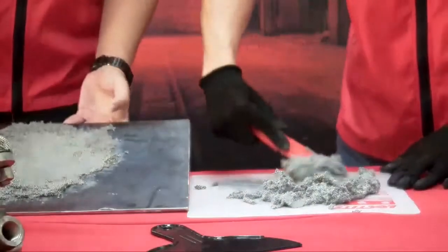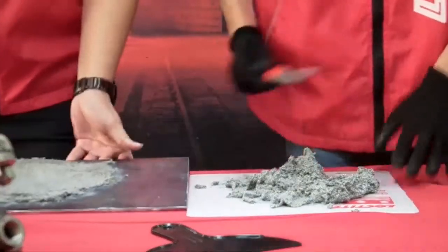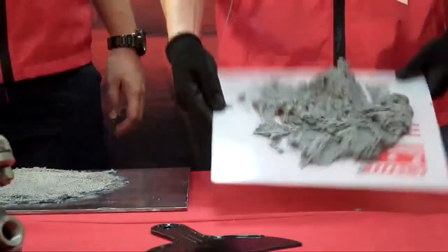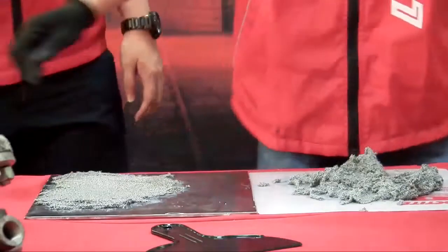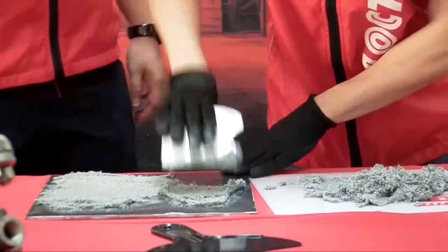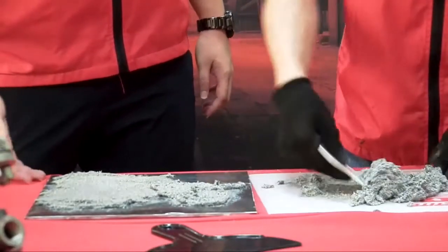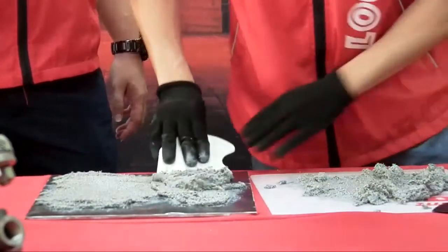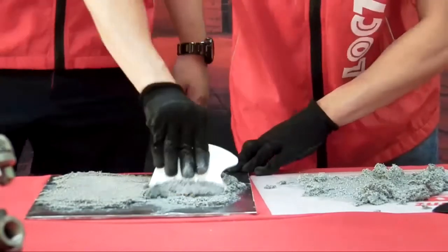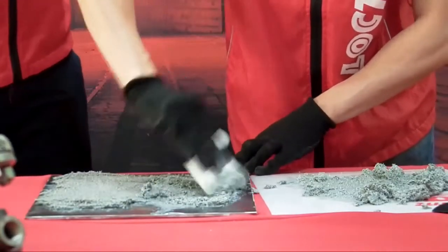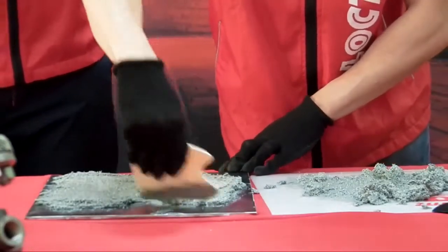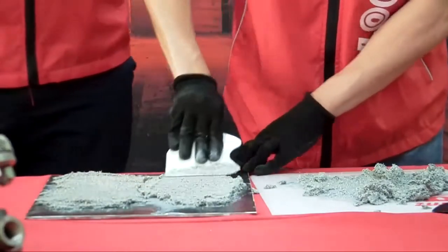Okay, I've already done the mixing. You can see I mixed it quite carefully. Like what Eng said, I'll try to apply to the metal surface first, so that you can see how easily this product can bond to the metal parts. Basically, you can coat this 7226 up to whatever thickness you desire. What we recommend is mostly a minimum of 6 mm. Yes, for these products. Okay, you can see I already applied this product onto the clean surface.